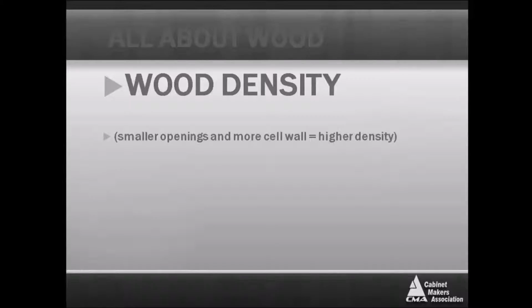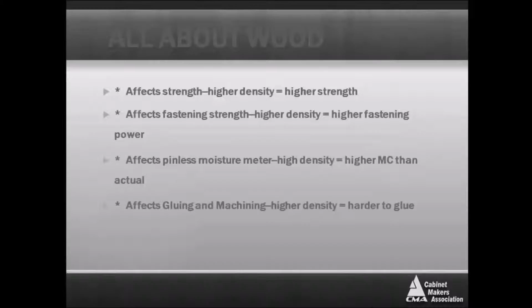Wood density. I talked about how when the wood cell has a thicker wall and less hollow space, we get higher density. That affects the strength. Higher density means higher strength. Higher density means better fastening strength: staples, screws, nails.